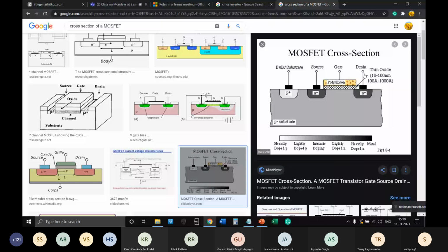First of all, you have to understand what is there around the source or drain regions. There are depletion regions around the source and drain. While the channel gets formed, and if you go beyond the threshold voltage or VDS saturation voltage, you get a huge depletion region over here. So this is P and this is N, and this junction is going to be reverse biased, and the reverse bias voltage will increase if you increase the biasing of the MOSFET beyond VDS sat.